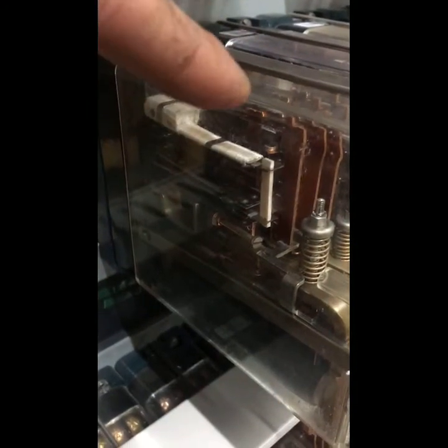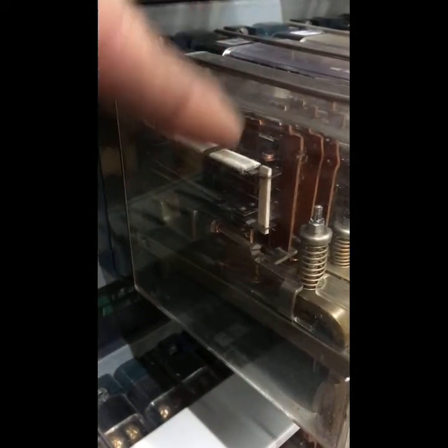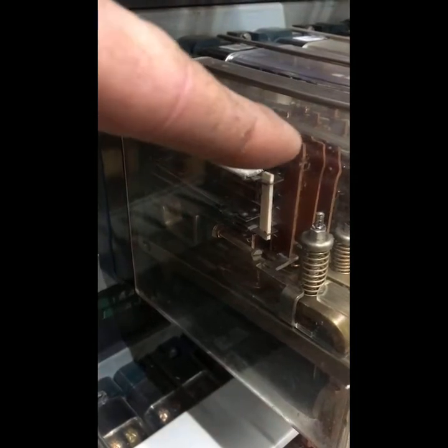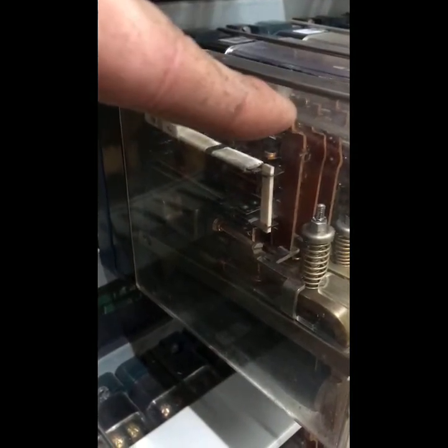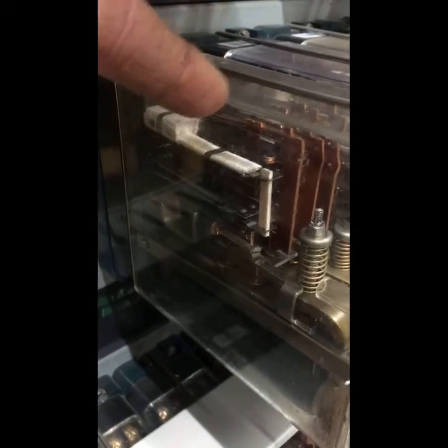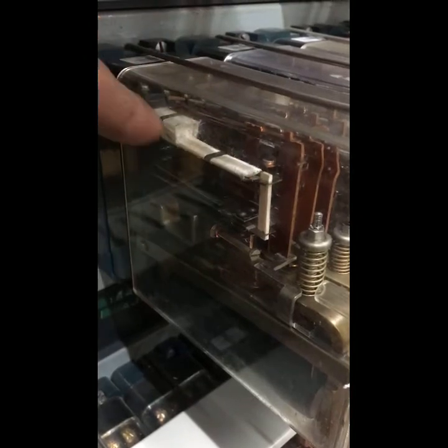But that's the hot part of it. But then you also have to cold prove it, so you also have to make sure it goes back to where it was, because what you don't want is a timer relay, once it's timed, staying stuck in that position. Otherwise, it's never going to time. The next time you need to use it, it's already there. So that's not safe, so we have to prove it's gone back, so cold proved.